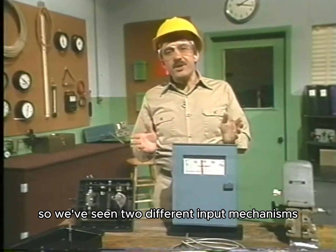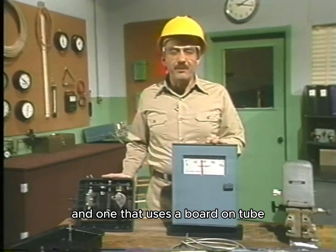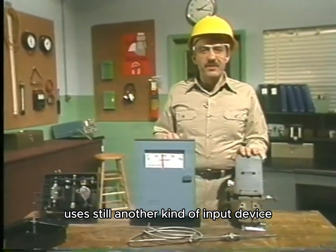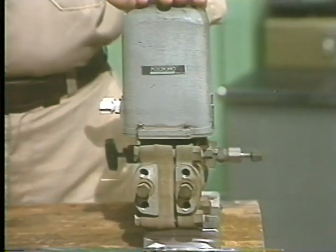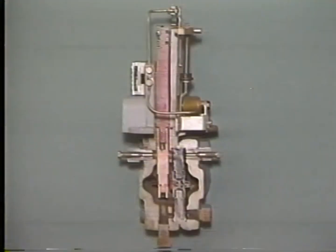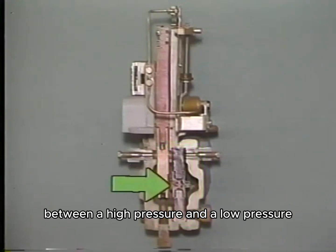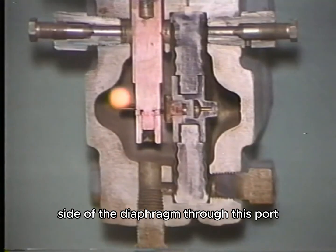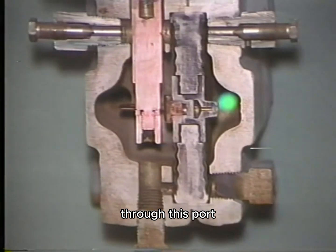So we've seen 2 different input mechanisms, one that uses a bellows and one that uses a Bourdon tube. Now, this differential pressure transmitter uses still another kind of input device, a type of diaphragm, which is encased in this housing. We'll use a cutaway of this device to identify the internal parts. The diaphragm here senses changes in differential pressure between a high pressure and a low pressure. The high pressure is conveyed to one side of the diaphragm through this port, and the low pressure is conveyed to the other side of the diaphragm through this port.